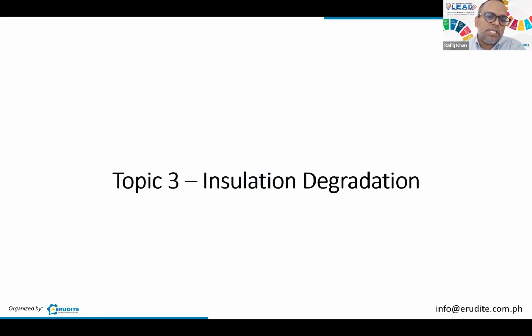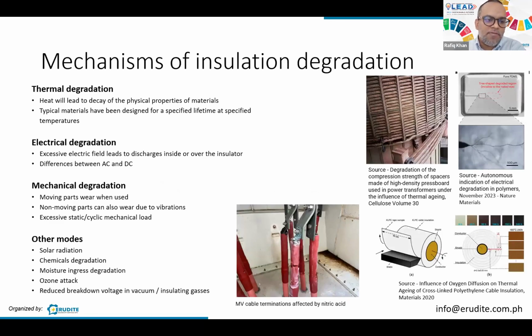Topic 3 is insulation degradation. This is something I learned from my former organization. They do a lot of failure investigations as well, and this is thermal, electrical, mechanical, and ambient. In their terms it is ambient, but I'm putting here as other modes. Thermal impact is quite prevalent in power systems equipment. Heat will lead to decay of insulation properties, and then you have a design lifetime that is reduced.